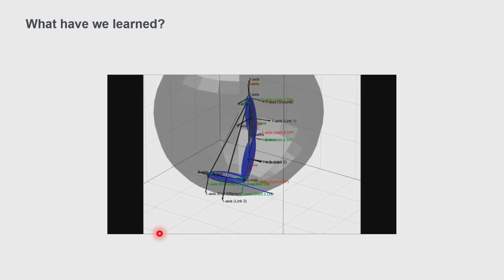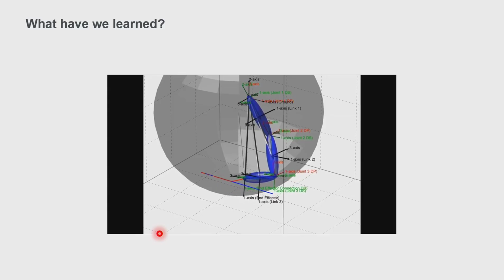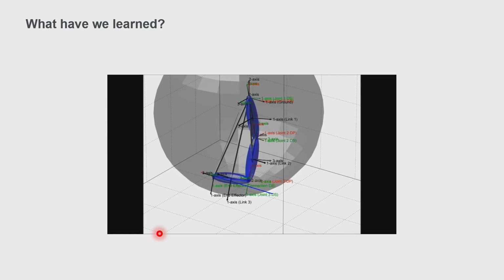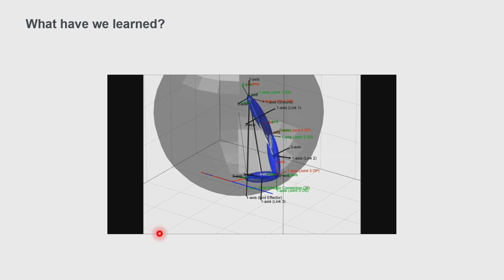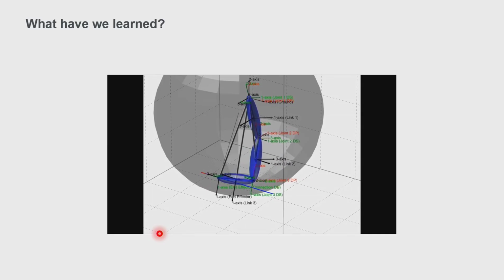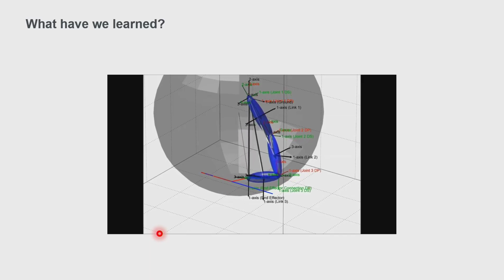This idea, right, if I have something that's rotating, and then I'm rotating it, you think that's the angular acceleration. But since my angular velocity is about this axis, the main effect is not creating a rotation about this axis. The main effect is about changing the axis of the existing rotation. So my angular acceleration points in a completely different direction. And looking at this can help build up that intuition and help you debug your future projects.